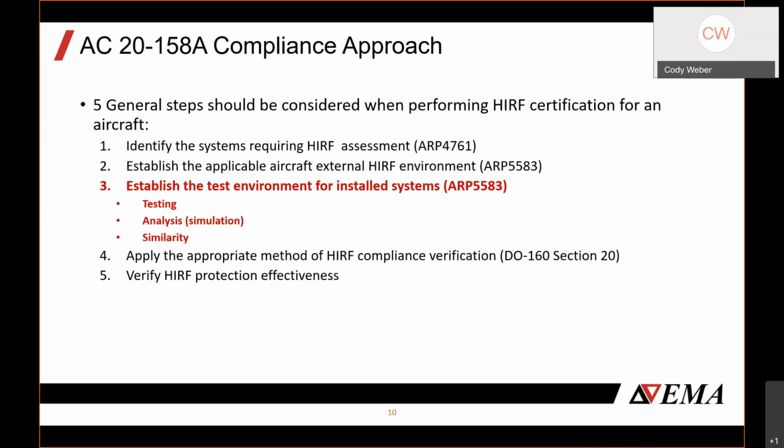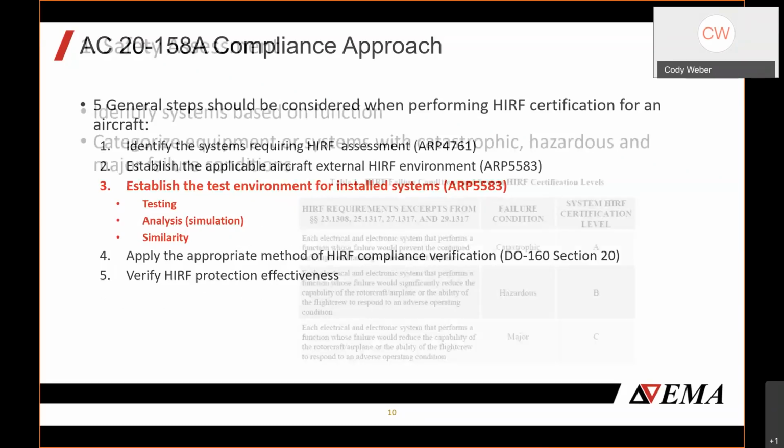There are 5 general steps outlined in the AC, and at a very top level, you have to identify the systems that require HIRF assessment. You have to establish the external HIRF environment appropriate for your aircraft. You have to establish the test environments for verification purposes on your installed systems. I've highlighted that one because that is the area I'm going to focus on today, establishing that test environment. And then, of course, there are the verification and compliance activities associated with steps 4 and 5.